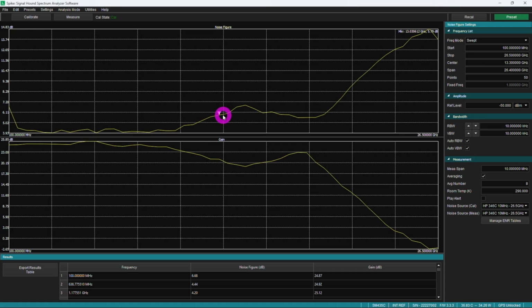And then once we're around over here, which is around 10 gigahertz or so, the gain of the amplifier begins to drop. And once the gain of the amplifier drops, of course, the noise then starts to climb pretty rapidly. Now, this amplifier is really only rated up to 10 gigahertz, which is up to here, and you can see it has a nice flat gain response just under 25 dB or so. There's a little bit of loss in that cable, which is not included. That's a different story on calibrating. But then once you have that, the noise figure is pretty flat. That does go up a little bit at lower frequencies as well.